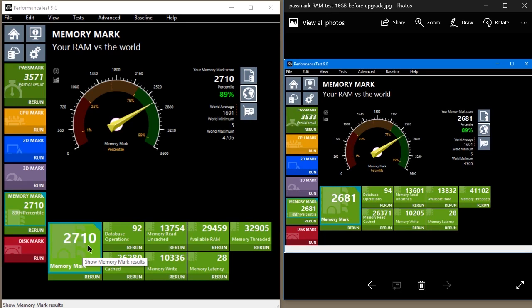And I didn't really expect much of a difference, even though it's 2400 megahertz. It's not really that big of an increase when it comes to working with RAM. Now, the old RAM, the 2133, that was using all 4 channels. That was set up as a quad channel. This is only set up as a dual channel. But quite often, dual channel may test worse, but it really behaves and performs pretty much the same when you throw real data at it. So that's something to think about.